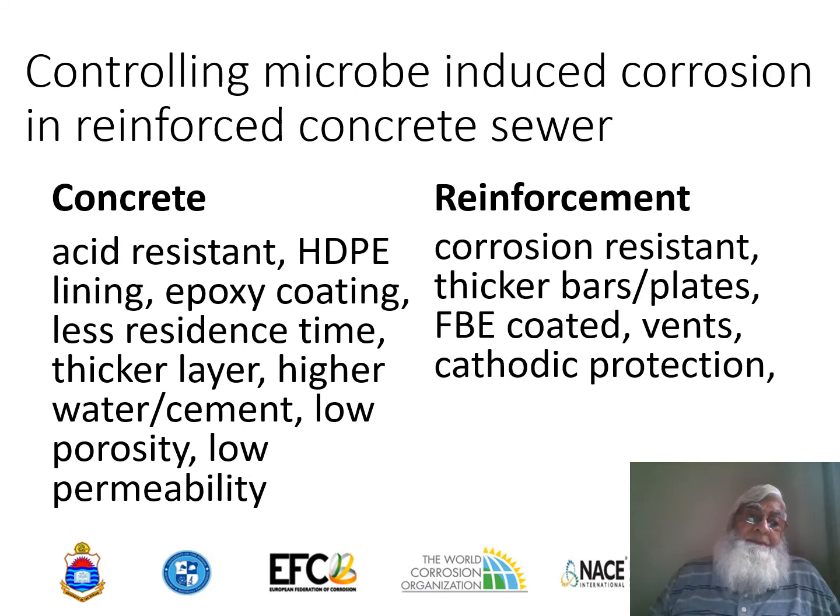And another thing is the residence time. Residence time is how long the sewage or dirty water is going to stay in there. If it stays longer, more bacteria form and colonize in there, and the extent of the microbial corrosion increases. And then thick layer means if you have a very thick concrete layer, more than the normal, it can give a longer life, right? And can also stay stronger and prevent the ingress of the bacteria down into the structure.